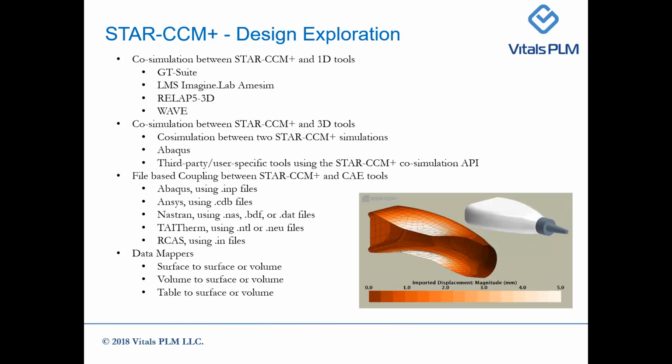We can also do file-based coupling between STAR-CCM+ and CAE tools like Abaqus using input files, ANSYS CDB files, Nastran files, and Python. We can also use data mappers like surface to surface, surface to volume, volume to surface, or volume to volume, or you can directly import table boundary conditions, and then you can use a table to talk between two different software.